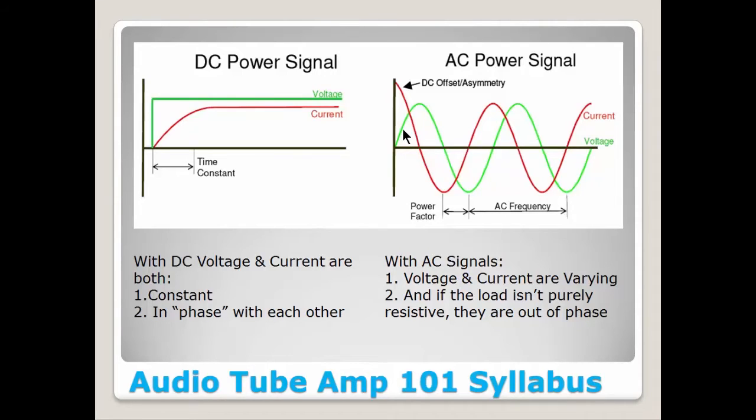So we haven't learned yet about inductors and capacitors, but one thing you will learn about them is they are reactive devices. And what that means is their characteristics change with frequency. And how that plays out for us here is like this voltage may be doing this, and the current here may be lagging it by a certain amount of time, and typically that gets measured in degrees. But save that for another episode.